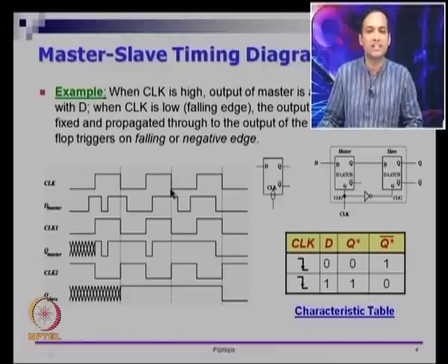So, when the next falling edge of clock comes in, at this point again D is 1, right. So, if you observe at this point, it is again at 1, and I will keep that as the value and continue that, keeping that value at Q till the next clock edge which is falling, which comes through.